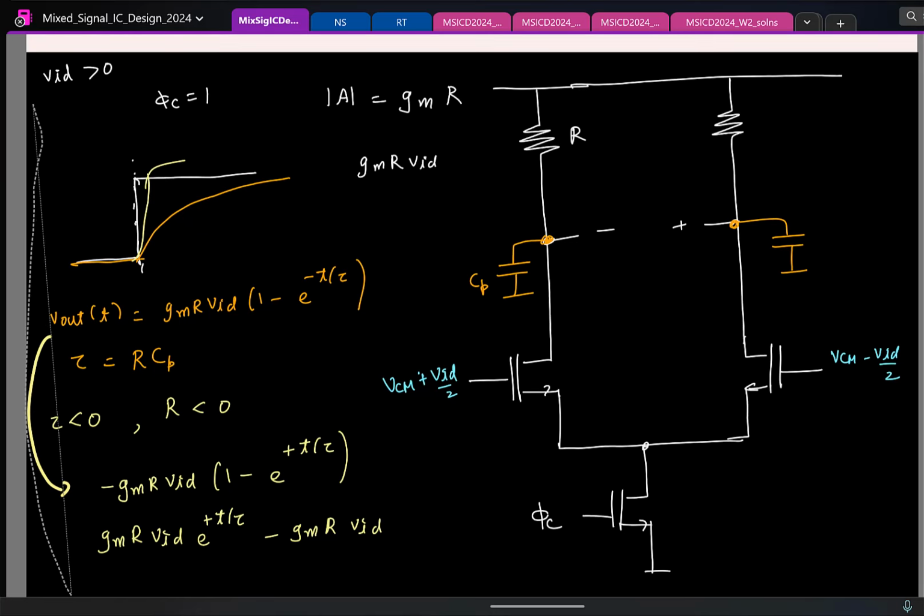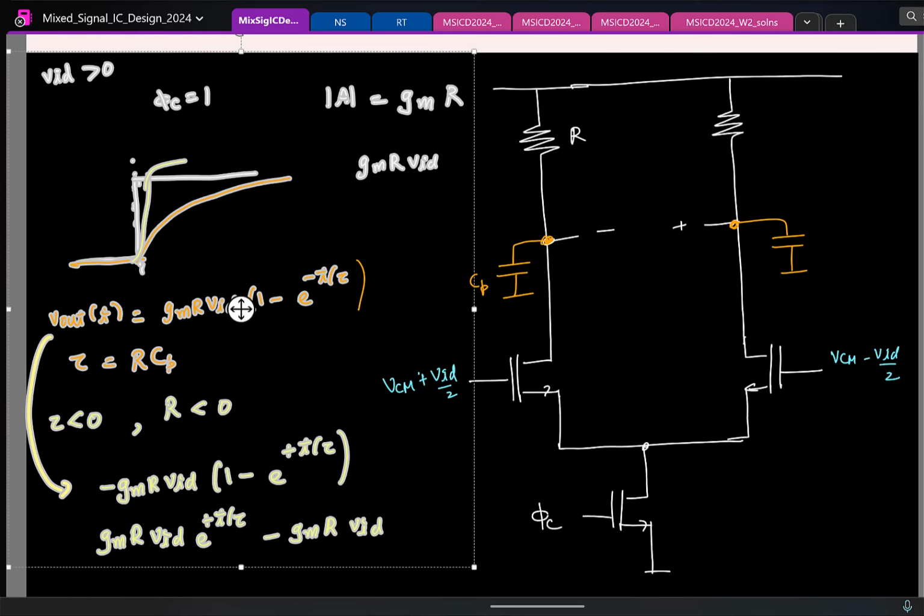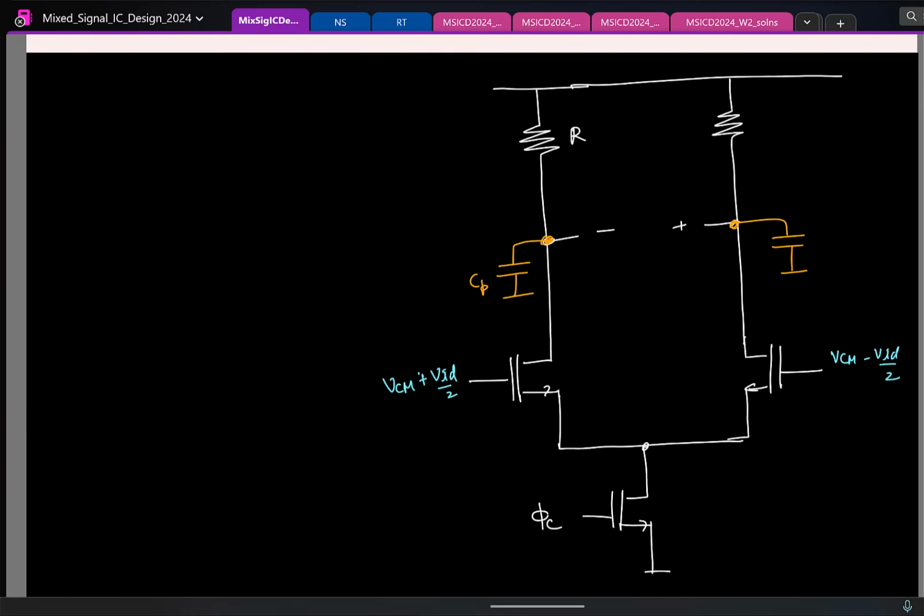So first of all, let's understand what does negative resistance even mean. Okay? So let us say I have somehow discovered a negative resistor. Now we are trying to characterize it. So try to plot the IV relation like this. If you apply a test voltage, what is the current drawn in this direction? Minus Vt by R. So what is the current in the opposite direction? So that's what a negative resistor is. If you apply a voltage, it should pump in a current.